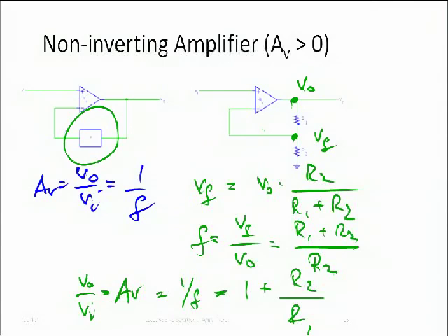Again, what we said before, even though the operation amplifier's gain, we don't even know the exact value, right? Remember that data sheet was all over the place. Sometimes it's 200,000, on a bad day it's only 20 or 30,000, right? But because it's large and we use feedback, then the gain, the closed loop gain, is set by just resistors. Wonderful.